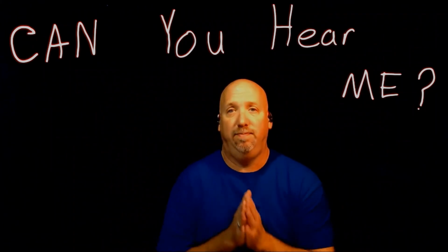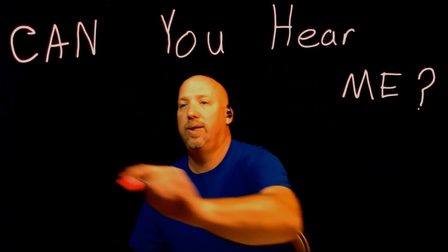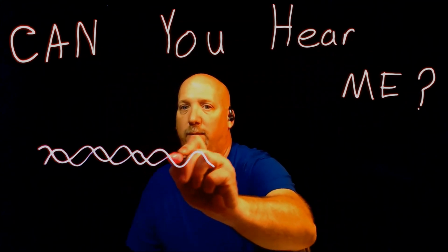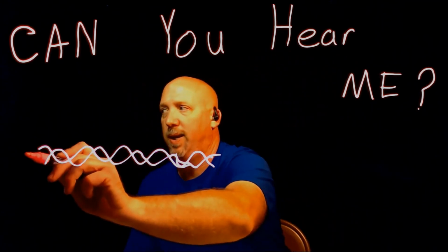CAN termination. The two twisted pair of wires have a 60 ohm resistance between the positive and negative circuit. It's achieved by placing 120 ohm resistors in parallel. So we have a twisted pair of wires. Ooh, that's a terrible wire. Twisted pair of wires. And then at one end,